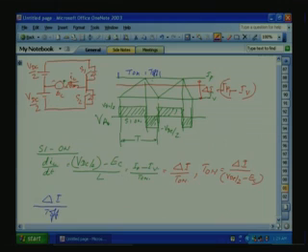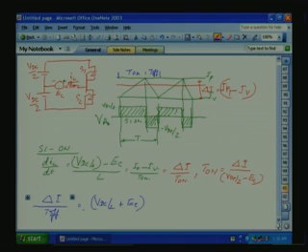So, delta I divided by T off is a slope, and it is equal to VDC by 2 plus EC. Here the slope is negative, but we are not taking the negative into consideration because we only want the T off period. So, we are taking the absolute value: VDC by 2 plus EC divided by L.